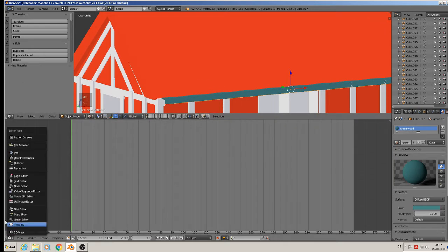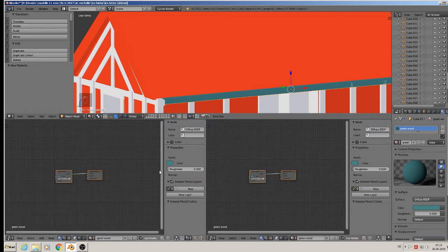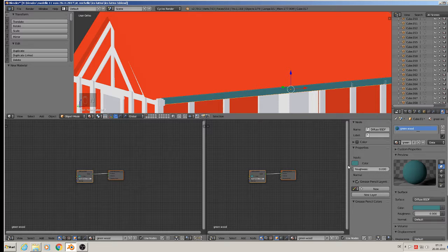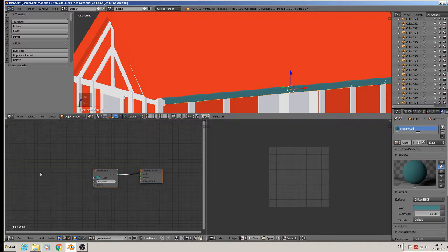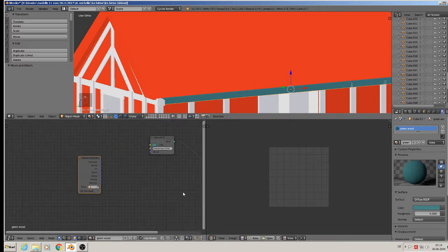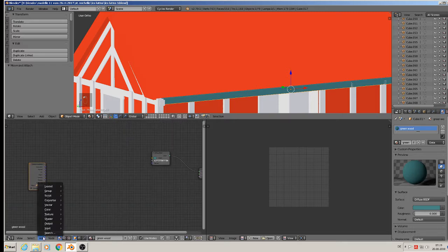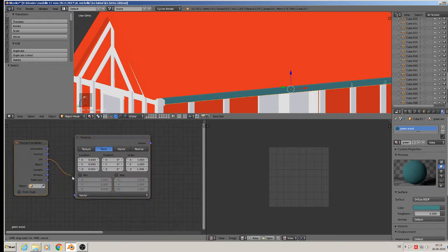as a 3D effect. So we take the node editor again, bring that to the side, close the panel, and to close that panel, bring up the UV image editor. Then we have our diffuse material. We take an input, texture coordinates. We take mapping, add vector mapping, connect the UV with the vector, click to texture.